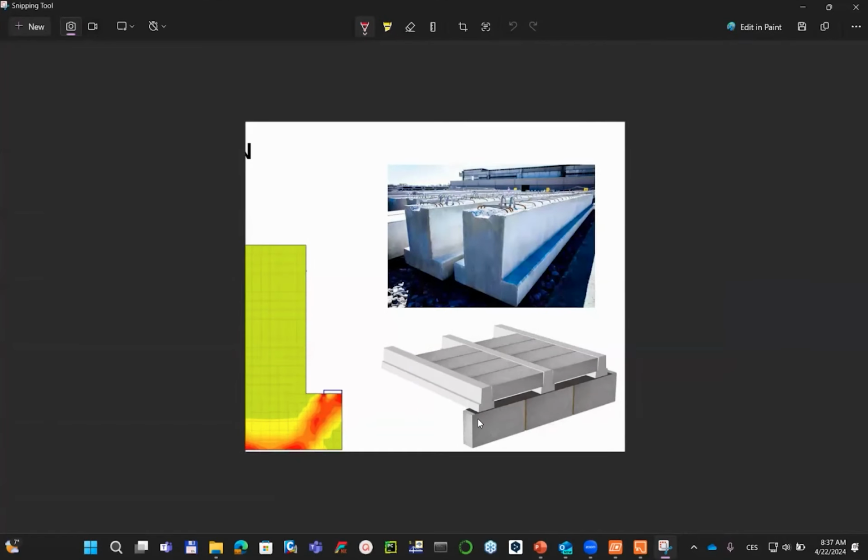In my model, I consider just a simply supported beam like that. So this is my beam that is laying here on the wall, and I'm cutting this part, and I would like to do the design and the code check of this reverse T-beam, because it's a discontinuity region. I would like to know how much reinforcement I need to cover the cracks which will appear here, and what the maximal force can be, or if I'm able to transfer this force via this model.